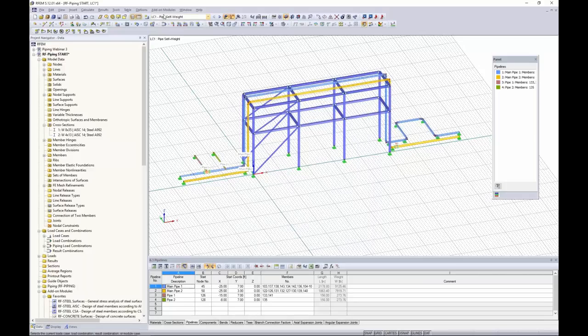Okay, so now that we have these load cases defined, you'll find those in our drop-down box available up here in our toolbar. We want to begin loading the pipes. So we'll start off, pipe self-weight, we'll just leave this as is. We won't apply any additional loads. Now the piping fluid. What I'd like to do is to select all my members to apply the piping fluid to.